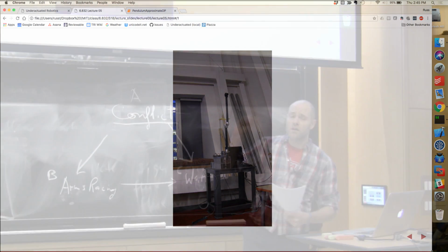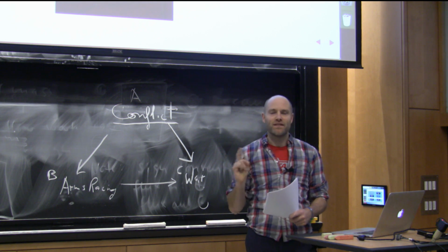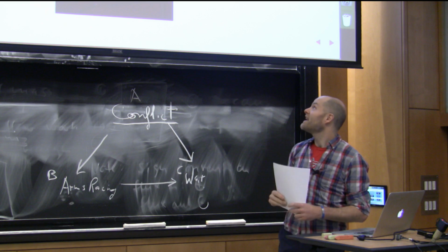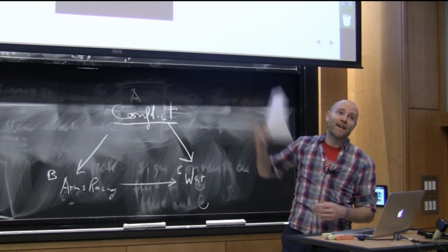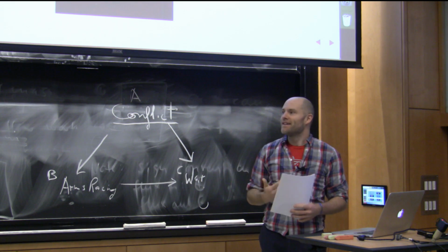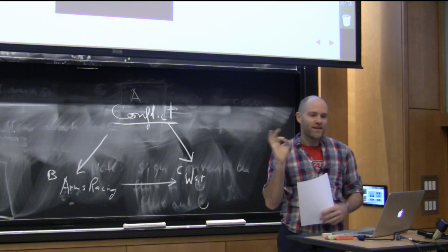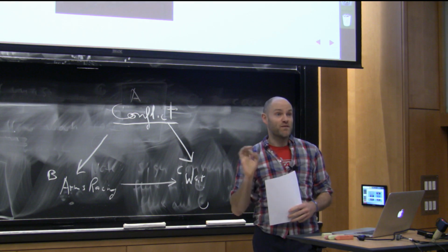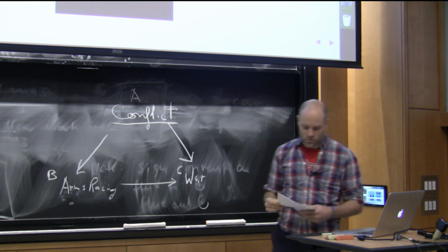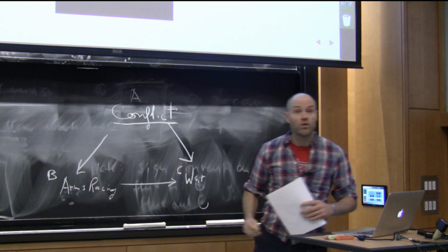The cart-pole turns out to be much easier experimentally than the Acrobot. And you can actually see that in the linearization. Not that many people have gotten Acrobots to work, actually. It's not impossible, but it's not that common because it's sort of on the verge of stability. It's on the verge of being able to control it. And we'll understand why. Cool. Any other questions?